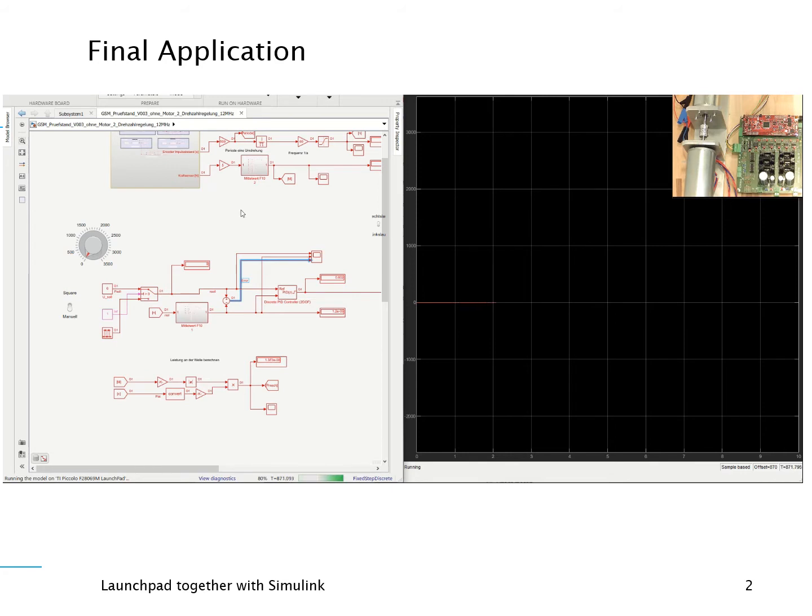And without recompiling the whole system, I can change the speed. And we see the parameters changing. We have desired speed, actual speed, and the error signal, and can directly change the parameter out of Matlab Simulink.